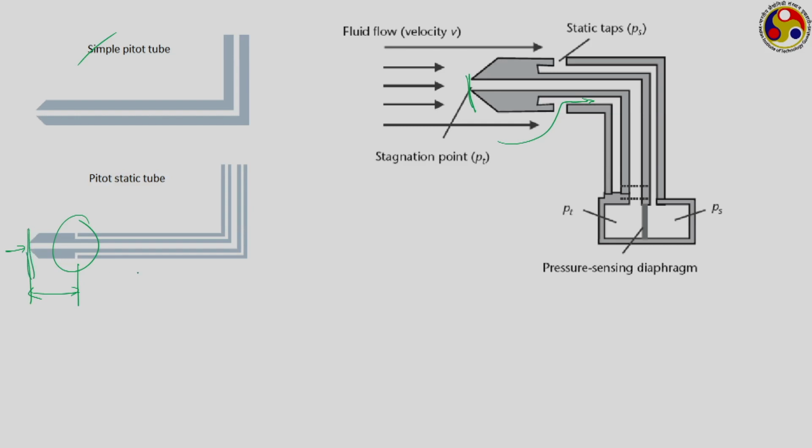This is what we call the nose, and this portion is the stem. If the holes are located too close to the nose, then, because at the nose position the velocity becomes 0, immediately after the nose the fluid accelerates, its velocity increases and pressure decreases. Whereas, when the stem comes into effect, the pressure will increase and velocity will start to decrease.